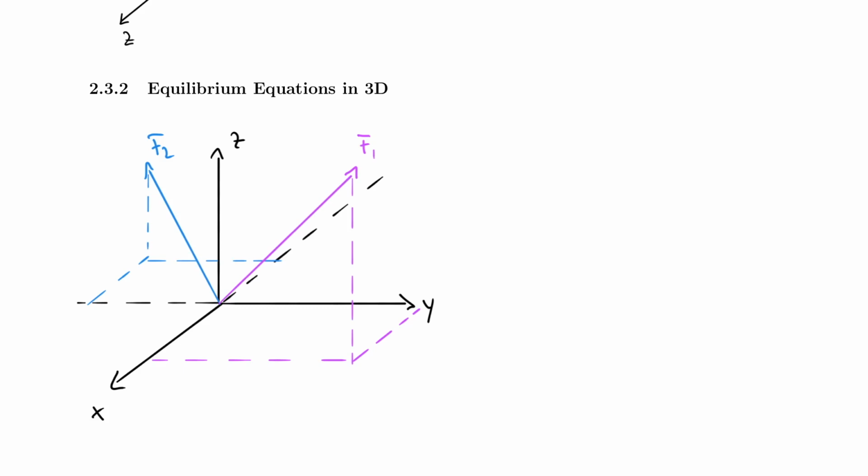And you may already notice that this system could never be in equilibrium, so I'm going to add a third force to it, because right now everything is just pulling up. Right? Let's take a look. This is going in the positive z direction, this is going in the positive z direction. So this system could never be in equilibrium. In fact, this should from now on make you clinch. You should say, why is there nothing to balance these two upwards forces?